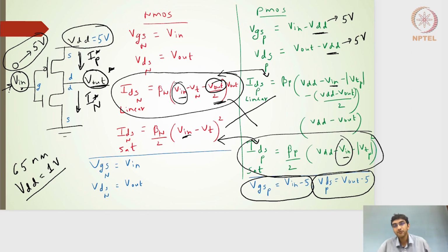But at this point, when we are very inexperienced, why don't we draw the current versus the output voltage profiles of the Nmos and Pmos graphically, and wherever those profiles intersect, that means the Nmos and the Pmos currents are the same at that particular point. That particular point will give me the V out and the V input.